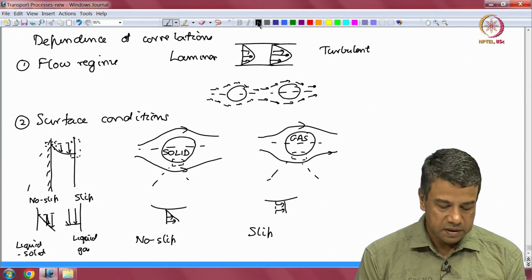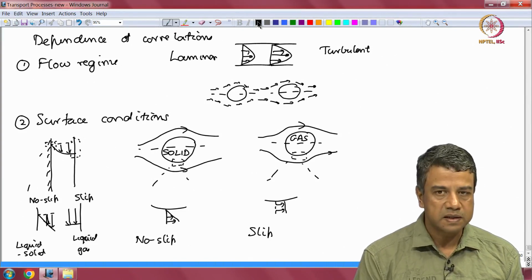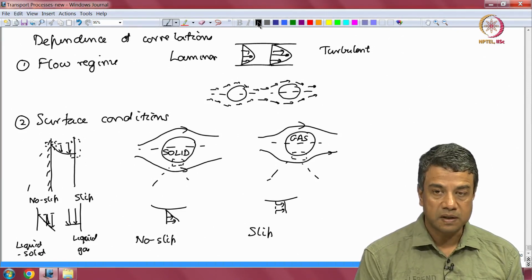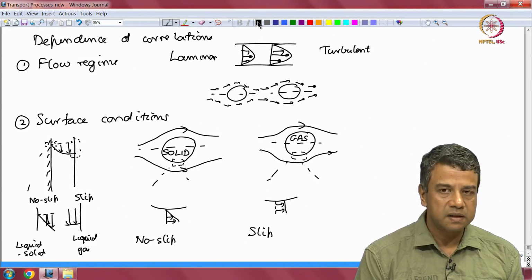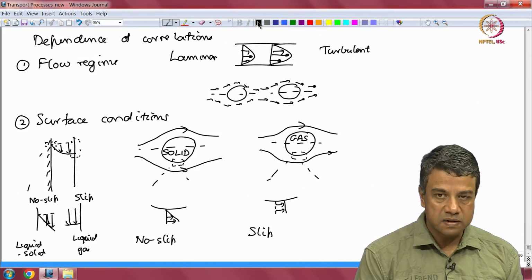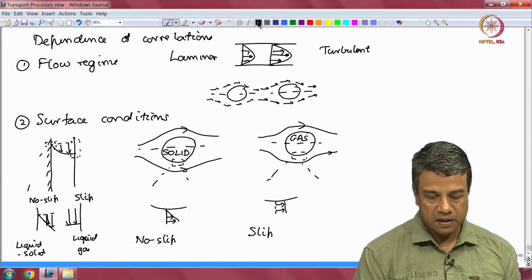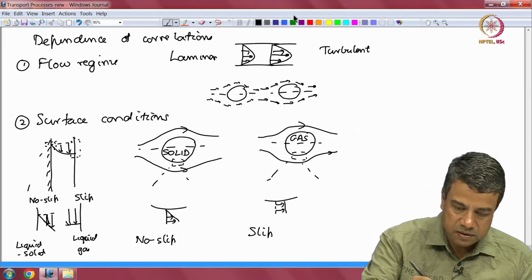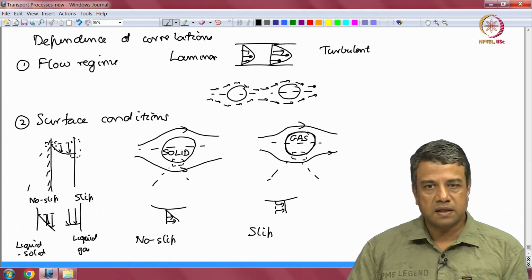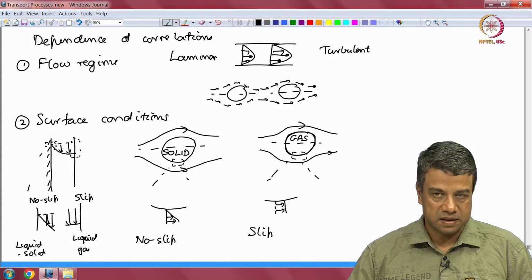At a solid surface, the velocity parallel to the surface is also equal to 0, which means that the strength of convection is decreasing to 0 at the surface. So, that is one set of boundary conditions at the surface. The other is at a liquid gas interface, for example. You can have a non-zero velocity in the liquid at a liquid gas interface. You take the case of a gas bubble, for example, that is shown over here. The velocity condition that has to be applied at the interface is the continuity of velocity on both sides and the continuity of stress.